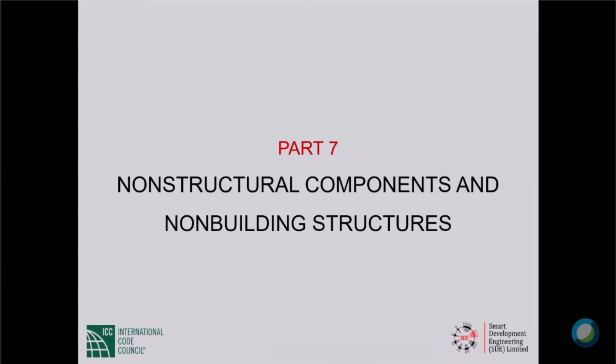ACI 318-05 allows the use of steel ordinary moment frame with some height and dead load limitations for structures assigned to seismic design category D and E. That is true. Does BNBC 2020 allow the use of ordinary moment frame for seismic design category D with similar limitations? I have not checked into that, but Dr. Rakib will teach a course on the steel chapter of BNBC. Whether it's one course or two, I don't remember now. So I'm sure that will be cleared up.